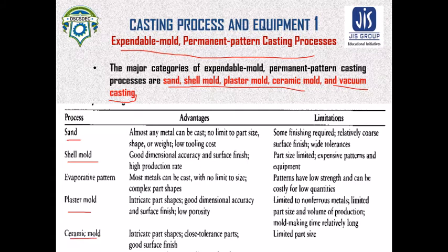One by one we will see the advantages. The advantages of sand casting are that almost any metal can be cast, there is no limit to part size, shape or weight, and tooling cost is very low. So this is the advantage of sand casting.